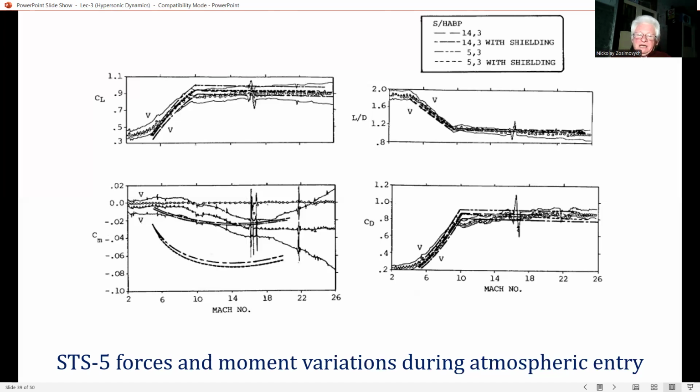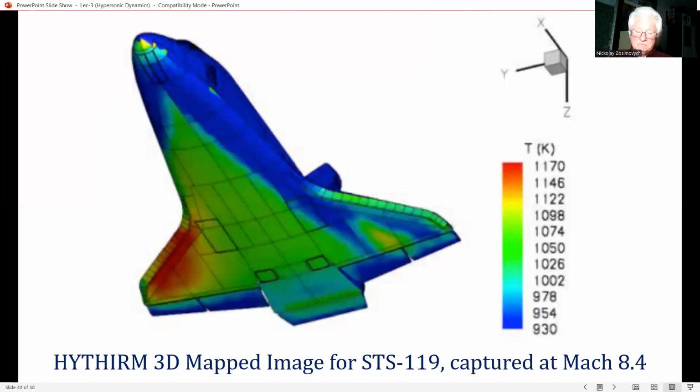The discrepancy in the moment coefficient calculation is caused by flow field chemically reacting effects, not included in our HABP, and not reflected in the NASA pre-flight prediction data, which are largely based on cold flow hypersonic wind tunnel tests.